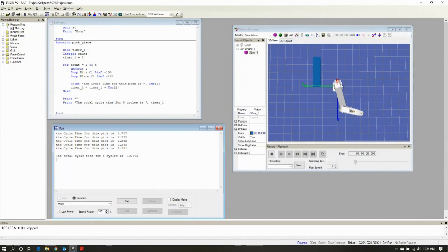So in this particular case, maybe if we used a combination of arms, a righty and a lefty, it'll affect our cycle time because now joint 2 and joint 1 would be moving simultaneously. So my pick is a great example to use as a lefty arm. The way I can force that is on the end of my command, I can say /L.